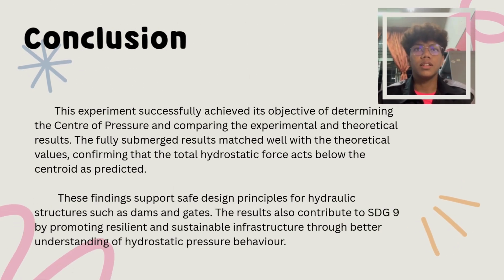In conclusion, this experiment achieved its objective by determining the center of pressure and comparing it with theory. For fully submerged conditions, the experimental values between 0.1120 meter and 0.1450 meter match well with the theoretical range of 0.1056 meter to 0.1120 meter. This confirms the total hydrostatic force acts below the centroid as theory predicts. The results support safe hydraulic design and SDG 9 for resilient infrastructure.